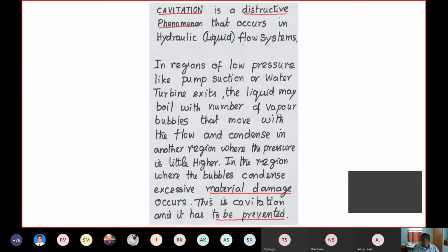So these mechanical devices, refrigerator is one. In many houses they run for more than 10 years without much maintenance. Okay, so here it should run at least 5 years, 5 to 10 years. But a heavily cavitating pump impeller may run for a few months only and it will be eaten away. So material damage. Second one is the efficiency falls down. The third one, vibration and noise. So maybe these 3 points you have to write.